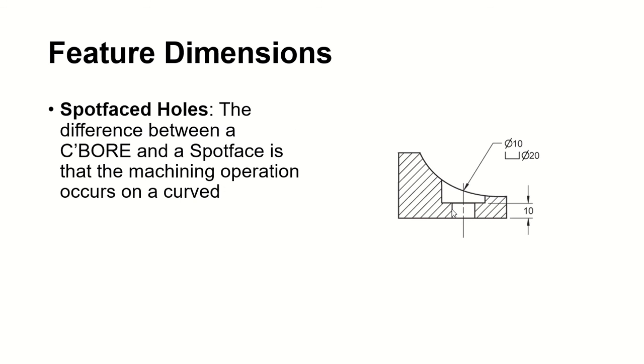That's for the spot faced hole. When you look at the dimension, drill, counterbore, and from here to here is your thickness. It's significant because it's 10 out of the total from here to here, so that's pretty significant. So we give the thickness instead of the depth.